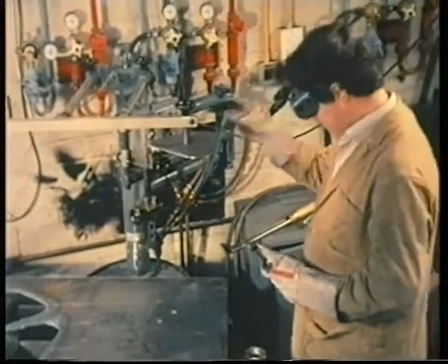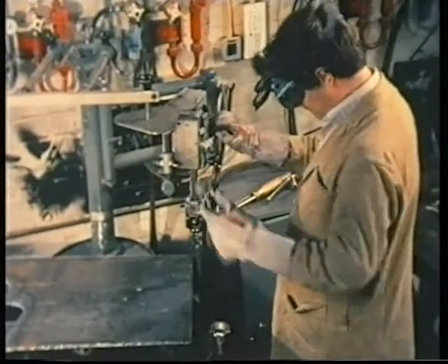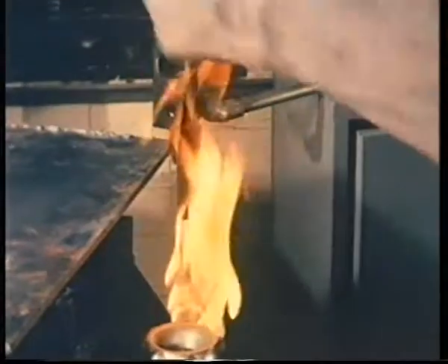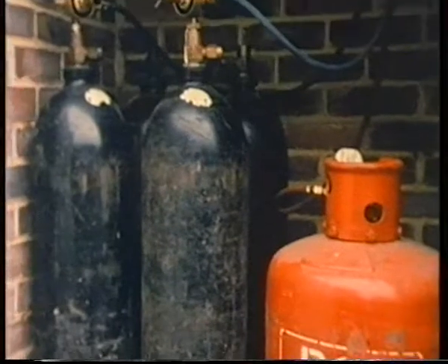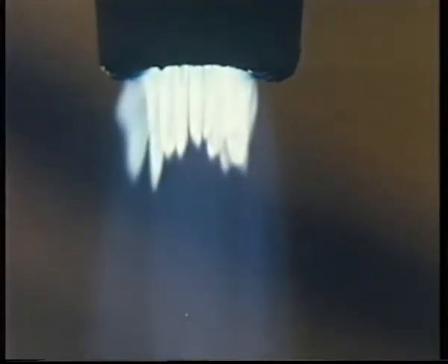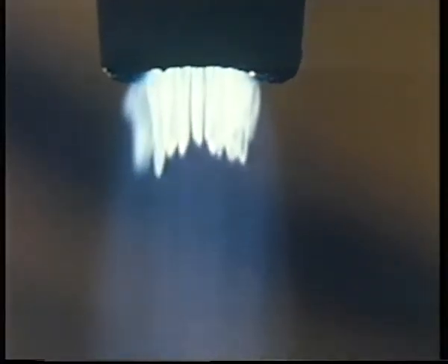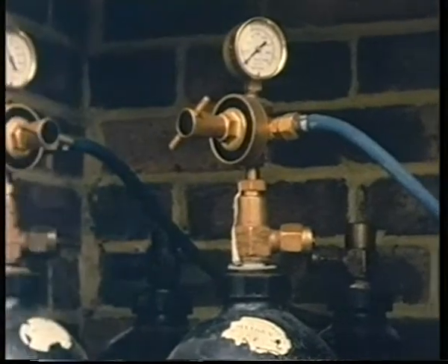The heat that's needed in flame cutting can be produced by burning any one of several different gases. Here, the fuel is propane. It's burnt with pure oxygen, which comes out of a cylinder. The flame is carefully adjusted until there's a series of short, blue, luminous cones. That's the heat source. To cut the metal, we use a high-pressure jet of oxygen. You can just see it in the middle. This oxygen is supplied from a separate cylinder.